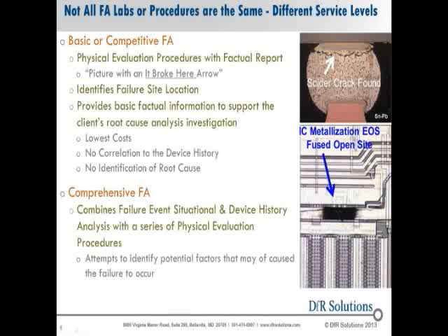Now then there's the more comprehensive failure analysis, where you get involved more with your failure analysis technical experts, and you provide them some of the background information and guidance on what you think is going on. And they can collaborate with you to develop, instead of just basic physical procedures, a series of physical procedures and evaluations that will hopefully lead us to a root cause. So this is where you work in partnership with the failure analysis lab personnel.